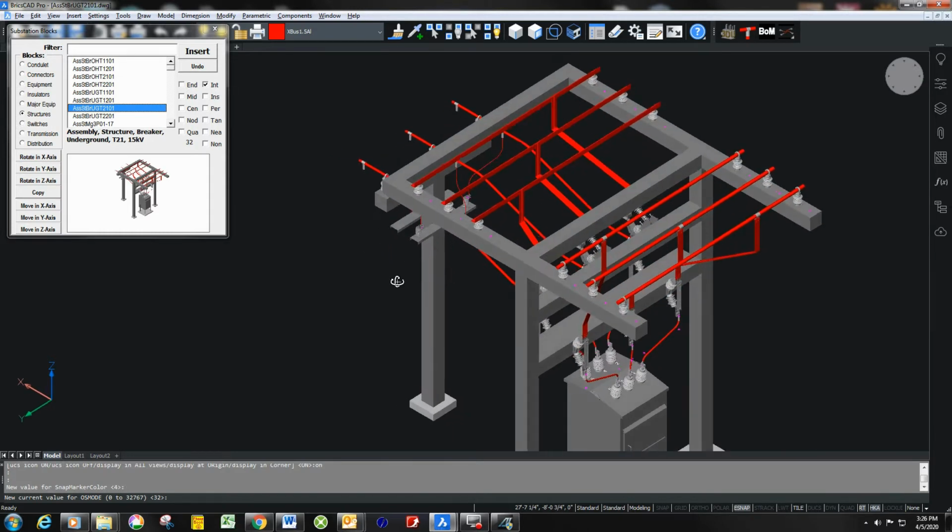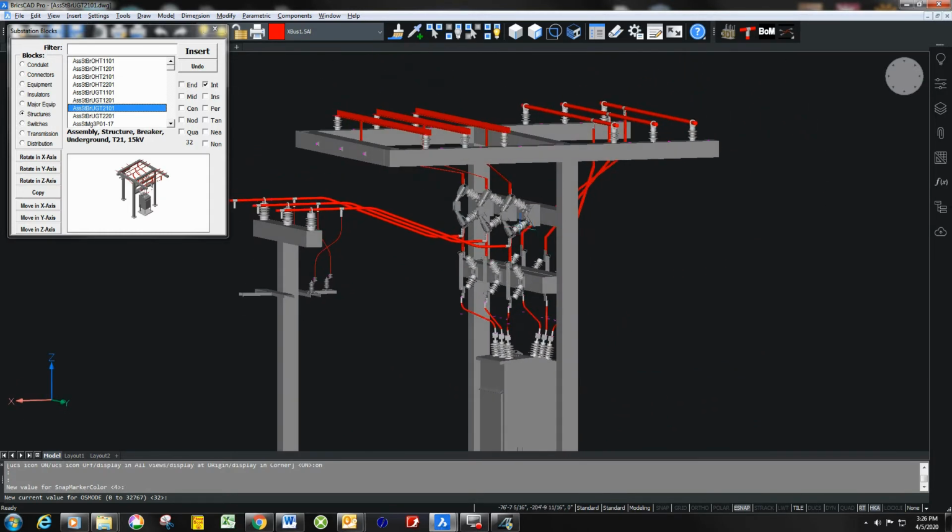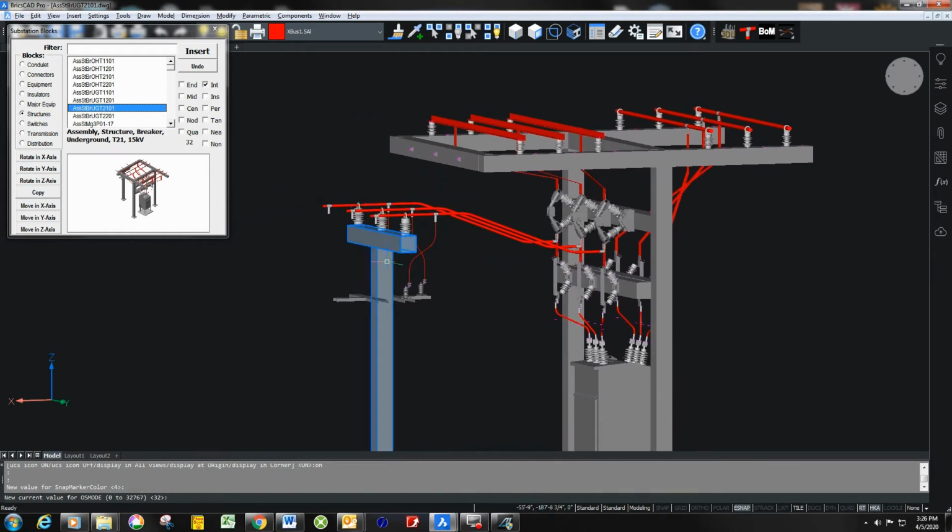Then we come over on the low side. We come across from in between the bypass switch and the isolating switch to a structure over here, a T structure that has provisions for lightning arresters, and then here is where we would tap to go. We would place, probably as part of the line construction contract or work order, your terminators here in the cable and make the connection up here to these terminals right here, or these connectors right here.